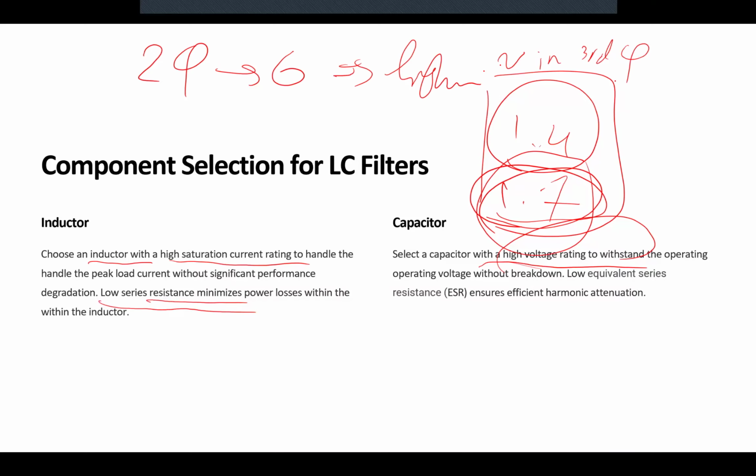Okay, you could search on that. This is based on practice, and I'm giving you this information. Based on your system, you know what the highest risk is, what the worst-case voltage is that your capacitor could face, and you have to pick a capacitor that can withstand that terrible situation. Make sense? This is the practical tip in designing.